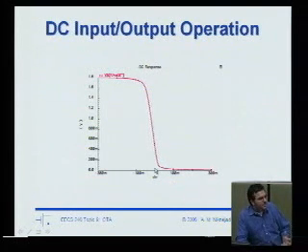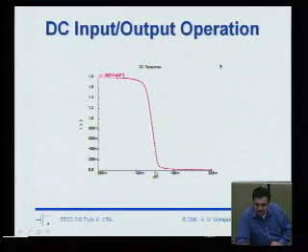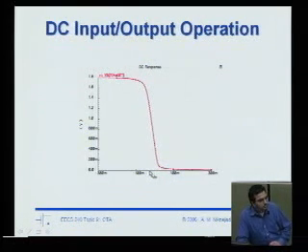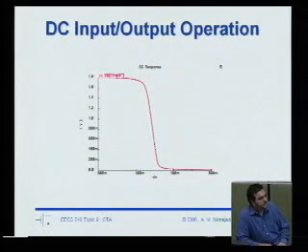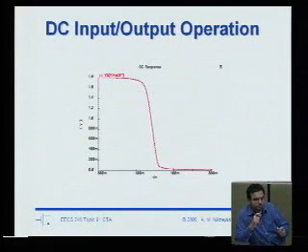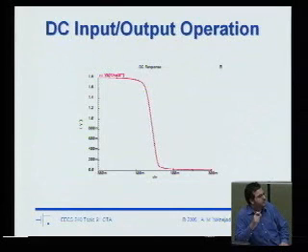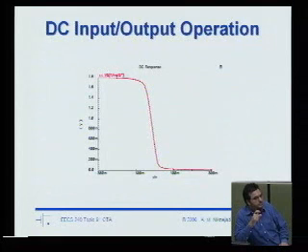But that's not really right? Because in transient conditions, my amplifier is going to see pretty large input signals, right? My diff pair has 0 differential voltage at the input. Boom. Sampling capacitor comes on. I see 500 millivolts, let's say. That's a large signal, right? And so what really matters to me is how much the output responds to that large signal input. So it's really the large signal gain that I care about.